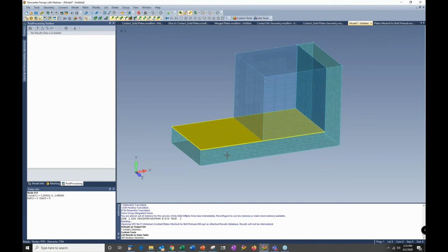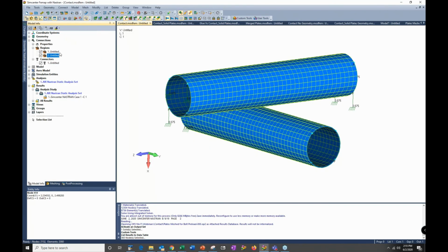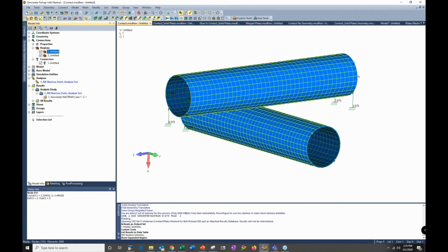Okay, phase 1 and phase 2 for shell elements refers to the top face or bottom face of the element, and you would visualize that by doing what I showed earlier, by using the transparent highlight or just the show normals, and show your region, show which direction your region is pointed. And if you needed to reverse that, you could do that in the same command.